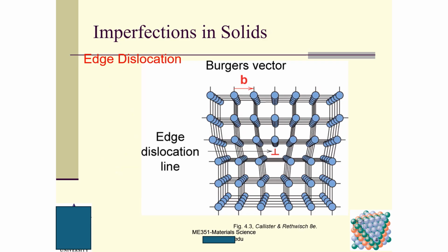I'm going to show you. And here, this edge dislocation. So here's the edge dislocation. This is 1, 2, 3, 4, 5, 6. So these are six complete planes. However, if we put an extra half crystal plane, like this one here, in between the third and the fourth one, we will have a resultant crystal structure like this figure shows.